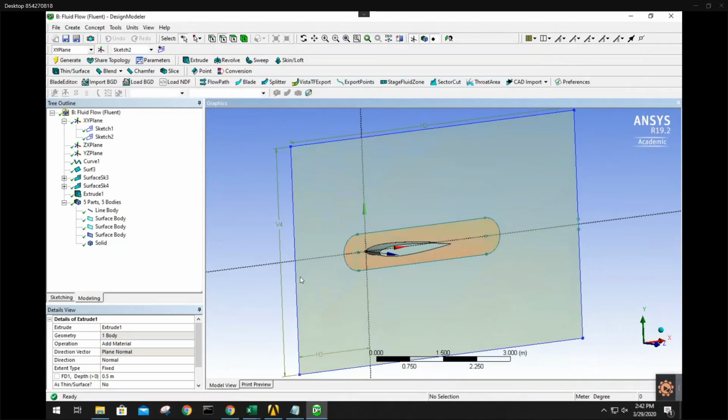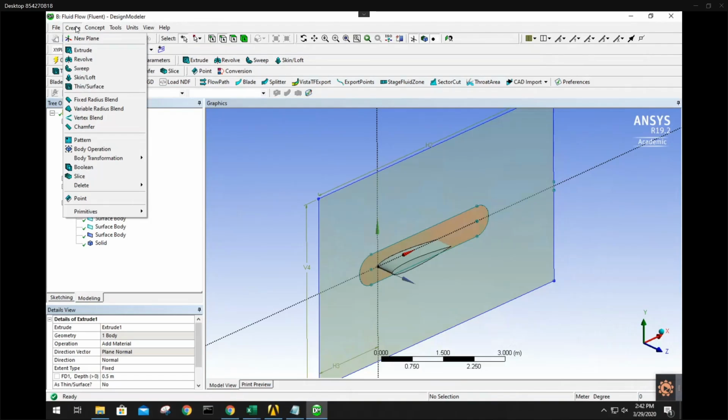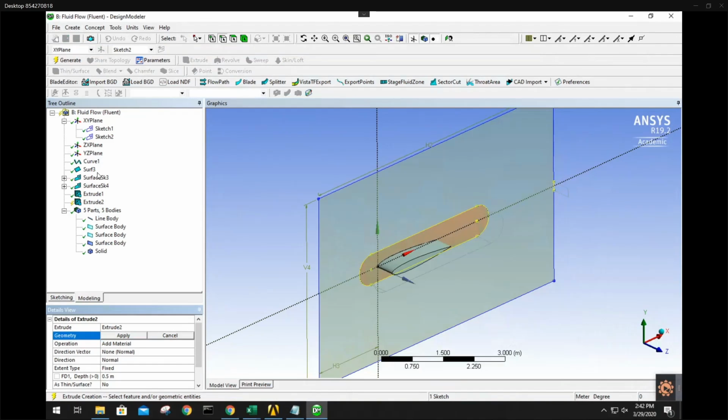0.5 meters, chord length 2 meters. I don't know what type of theoretical wind tunnel you're trying to use, but this is going to be mine. Then I need to do the same thing with my second surface. I'm not going to add material, remember. Keep it separate because we're going to do a Boolean operation. Normal to...